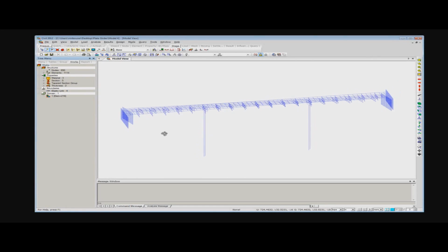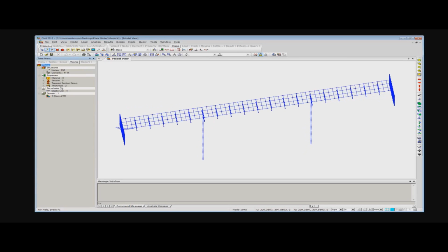Now we also defined these piles. For piles, it is exactly the same way. We select these nodes and then extrude them. Now is the time to define the groups. For groups, you can assign different elements and different boundary conditions to the different groups. So for that reason, you can simply select your structure, go back here, and then from your section, let's say composite section, and then come to the group, creating